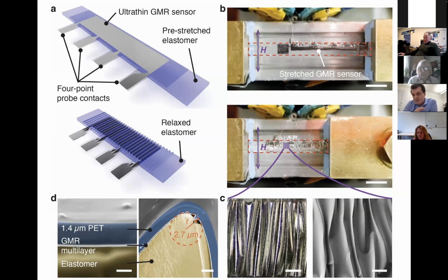So you measure some hysteresis curve. You have to understand how to describe it. And for this, you need a platform to start the discussion. And then you can refine it. So you are absolutely right. This theory, which Vladimir, for example, emphasized, yes, it does not include nanomechanics in a way. Striction is not there, which is very important, right? Because yes, we call something permalloy, but this is not permalloy in the sense of permalloy, right? It's still a magnetostrictive material that we are using. We are using cobalt. Cobalt is a magnetostrictive material. This is not yet there, but it's a platform to build upon, right?